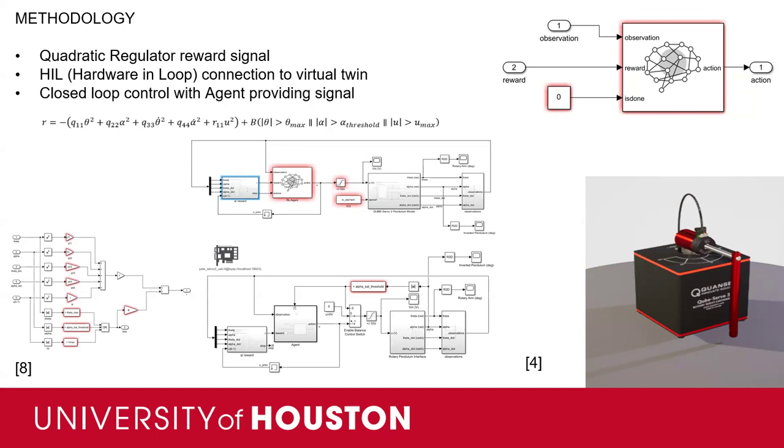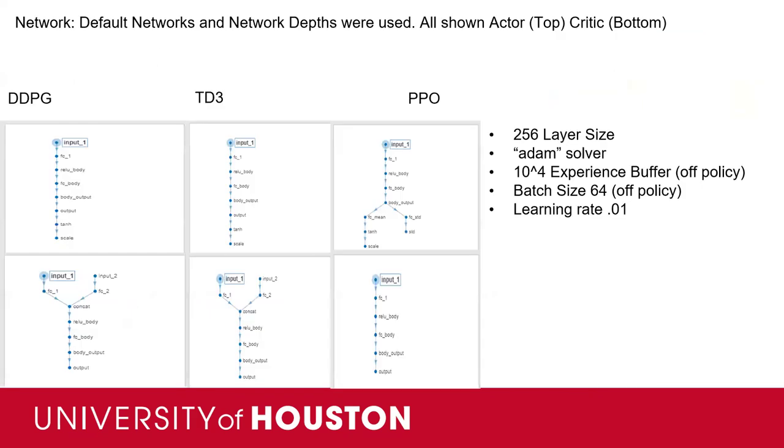Something that's really important and relevant to our simulations, we did not want the rotary arm to allow this thing to cross its own wire bundle. So all those terms are attached to a penalty factor that's part of the reward function. Now, that penalty factor can also additionally be tied to stop training criteria to locally stop the episode of the training session if you get that undesired behavior.